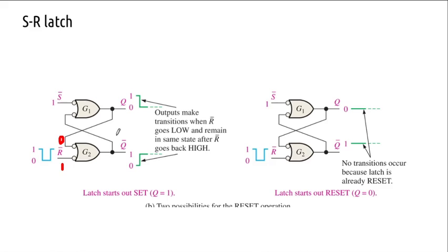The output is going to be still high. I feed back this thing here, the output is still going to remain as 0, because that is retained. So it retains the bit. It is storing that bit 0 that was given to it. It's latching. The same situation applies to 1 1.